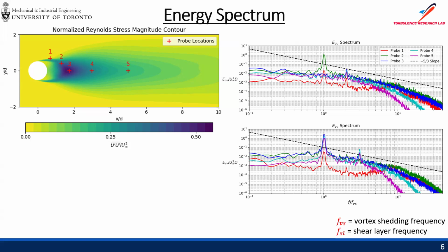The vortex shedding frequency is basically the wake that we saw on the last slide. We have a second peak. That's because there are two sides of the cylinder, right? The top and the bottom. Each side of it actually generates a wake shedding. So that's why we have a duplicate at double the frequency.